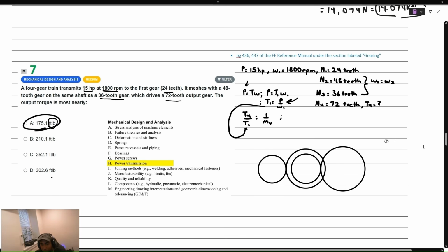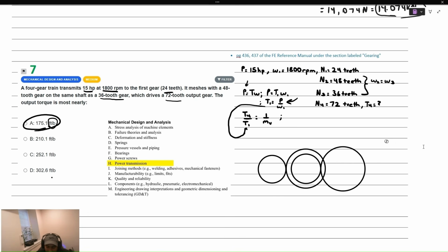You can see I drew our gear configuration over here, where I'm really drawing the pitch circles associated with each gear. The pitch radius is really a representation of the average radial location of the contact point. So when gear 1 and gear 2 are meshing together, their contact point will travel along a line.